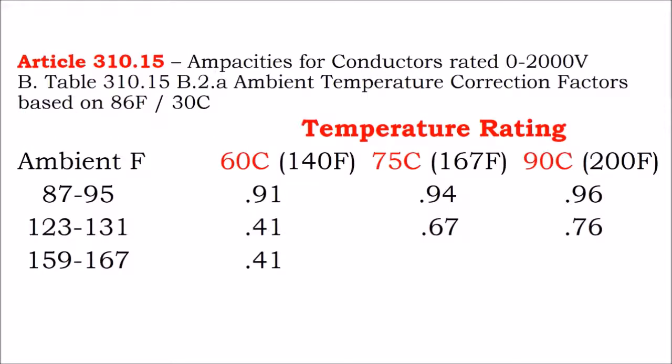So just because you have a 60 or 75C cable and it might have all the ampacity allowed for your application, if it's going to be subject to direct exposure to sunlight, you can't just oversize the cable to reduce its temperature. You need a cable jacket that is rated for that elevated temperature.